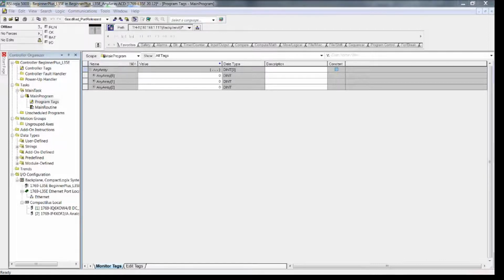The least significant bit of the lowest DINT sucks in a 0 or a 1 from the source bit, and the most significant bit of the highest DINT pops its value out to wherever it came from into bit space. I had several diagrams in the manual to illustrate this. And I want to remind you again that a left shift moves the least significant towards the more significant.